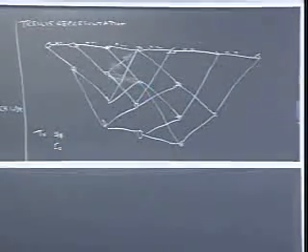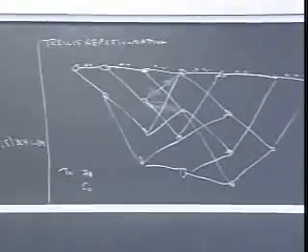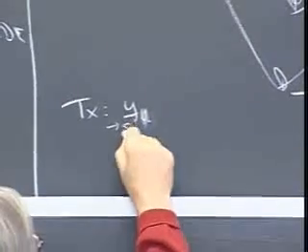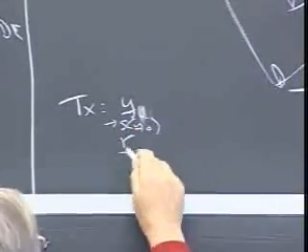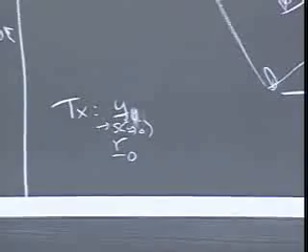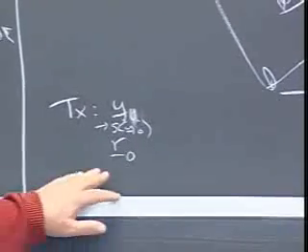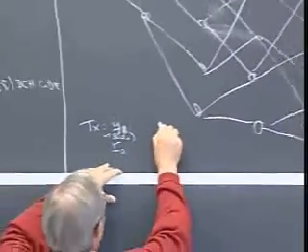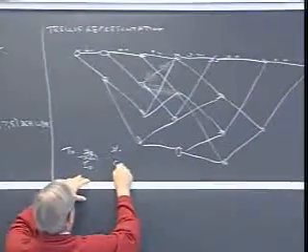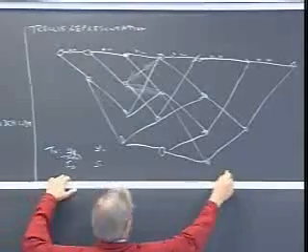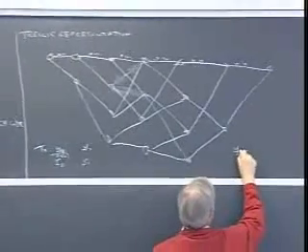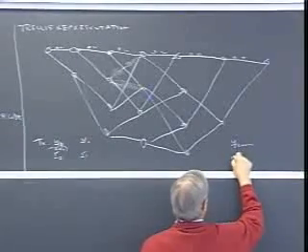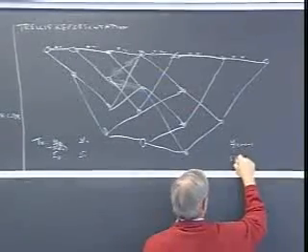If we were on a binary input additive white Gaussian channel, this would go into the 2-PAM map, plus or minus alphas, and be received as 2 real numbers. And we do the same thing here. Y1, we receive R1 and so forth up to y k plus nu minus 1.